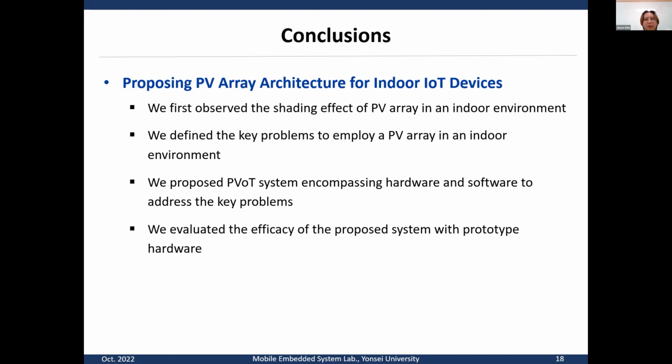It has the varying resistance depending on the ambient light, and it can sense the light. But I don't know, some others might use the voltage sensor instead of the light sensor, right? Because they sense the voltage of the capacitor, so they can have some reconfiguring capability. But using the photoresistor is a very interesting perspective.